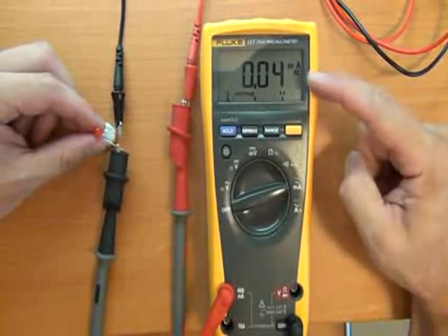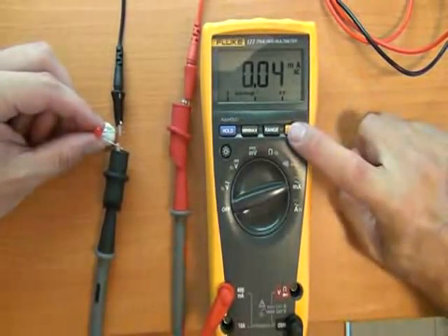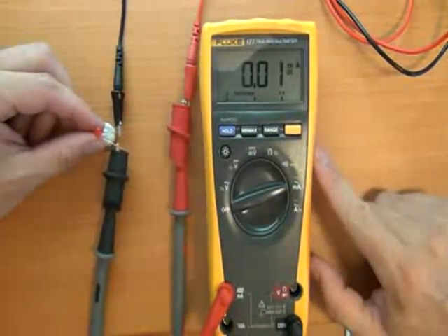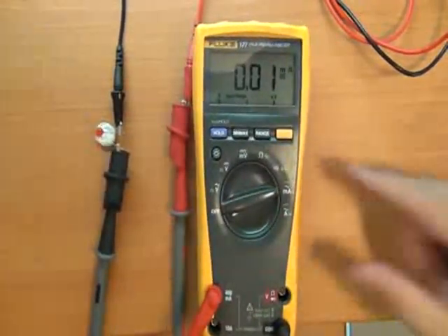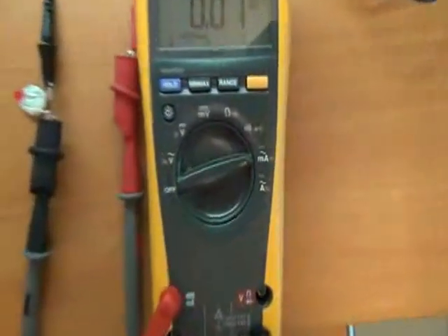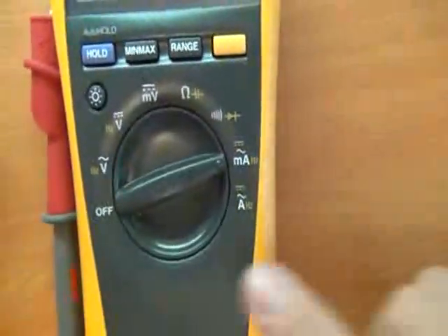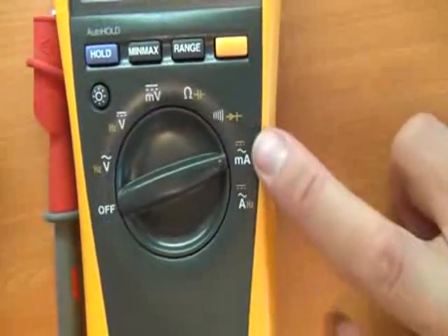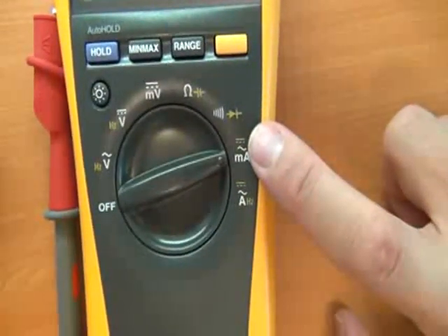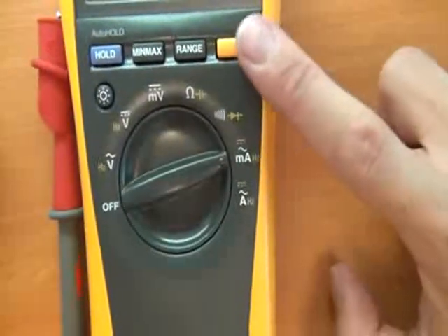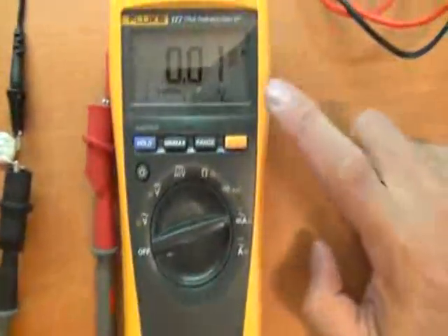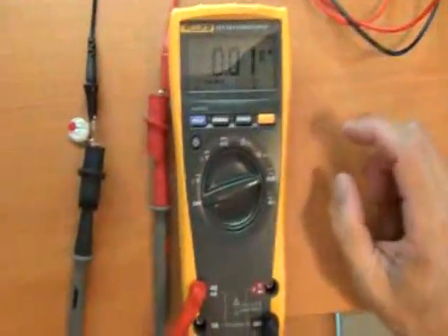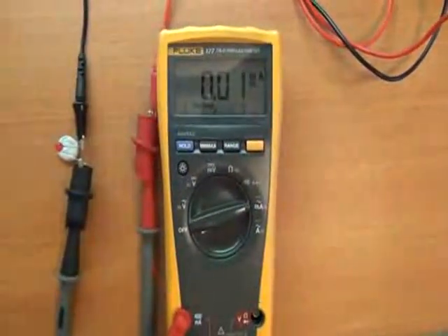Again, note it defaults to AC. We push the orange button to give us a secondary function, which, as you can see on here, hopefully the light's not obscuring it too much. I'll tell you what, I'm going to come in for a quick view just so you can see that. As you can see, the secondary functions on the current readings here are the DC ones. The straight line with the dashes underneath, and that's reached by pushing that button over there. And as you can see, we've now got DC. Okay, so let's come back up and have a look.